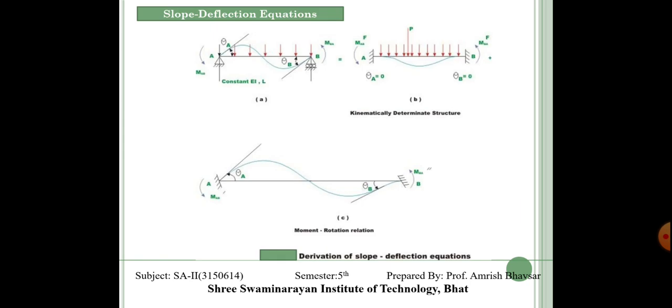So, let's try to understand the basic thing. If both of our supports are simple supports or hinge supports, then there can be rotation. But if both supports are fixed, then the rotation at the support is 0. So we can see in these figures that in a fixed beam the slope is 0, and in a simply supported beam there is rotation at support A.